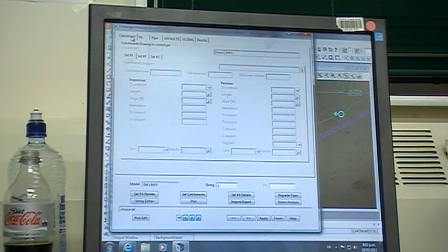You have to work out an individual flow per lot, based on 3 people per house, etc., and then work out how many lots are going into each pipeline, and you have to manually enter a value for a flow that's going in at that point, whether it's being added to the pipe or the pit. Okay, so that is changing.